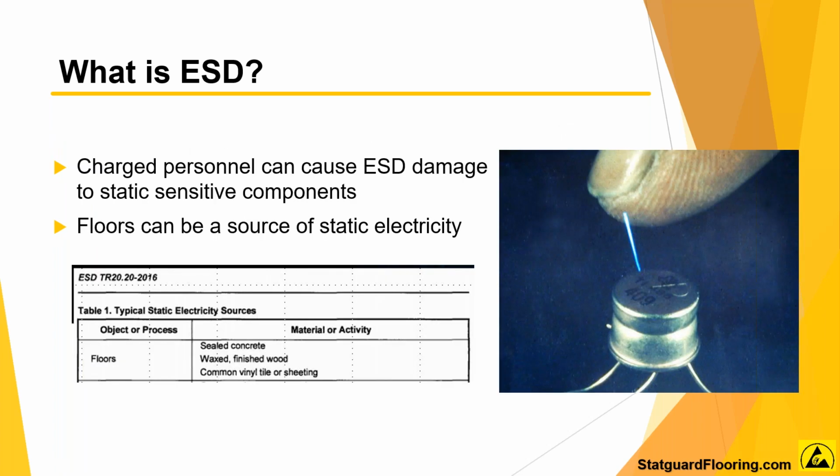Most certainly, ESD is a concern for any sensitive electronic device or equipment, and ungrounded personnel can induce charges to sensitive devices. When the wrist strap is impractical, there are ESD foot grounders or ESD shoes that can be used to ground the personnel. These items are effective only when used in conjunction with a properly installed ESD flooring.